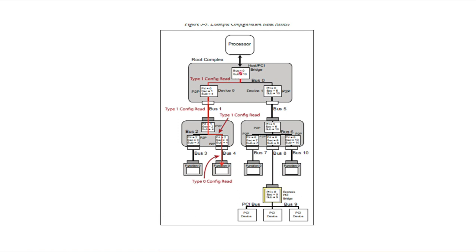When it sends the config packets, all the devices must have entered the L0 state. L0 state is the state where the actual packet transmission occurs. Link up has occurred, then data link up is achieved, where all the flow control packets are exchanged. Then this host bridge issues the config packets to device 0.